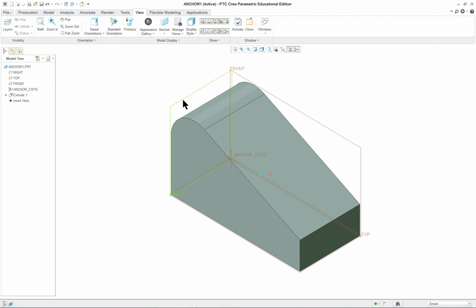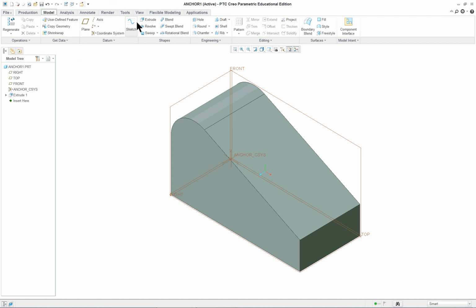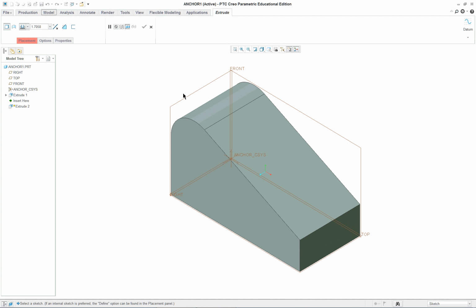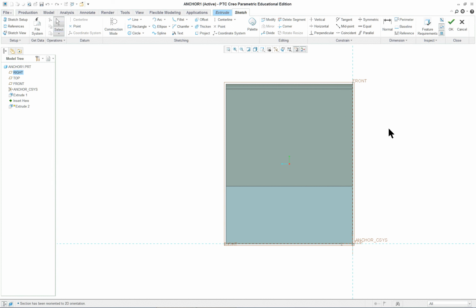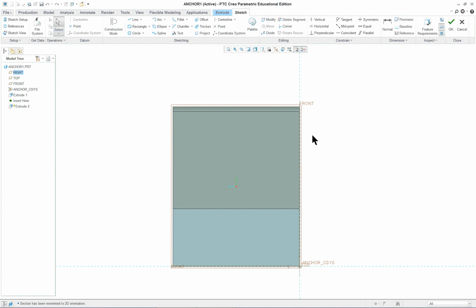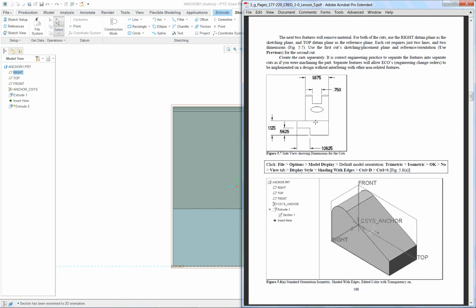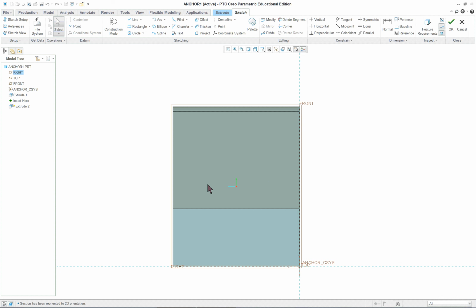So we're going to select, well, for the sketching plane, I'll tell you what to select. We're going to give the command first. So pick extrude, and then select the reference, the remove material, and then the reference for sketching. And the arrow showed we were sketching or looking in this direction here. So if I click on sketch view, it'll turn it. And my most important thing here, again, is paying attention to the fact that I've got my orientation the same, so I know the cut's going to be out of the left-hand side, right in here.